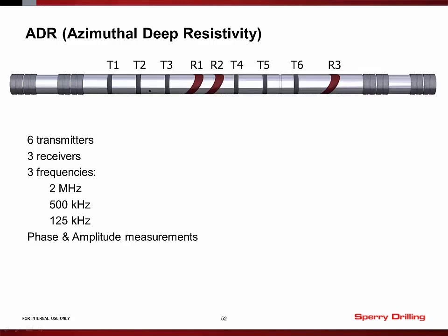That is, rather than making an average resistivity measurement from all directions around the borehole, the measurement is actually sensitive to just one side of the hole. So as the tool rotates, it effectively can scan around the borehole, producing an image, but more importantly being able to distinguish between resistivities in different directions around the wellbore.